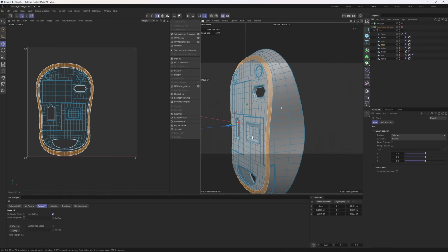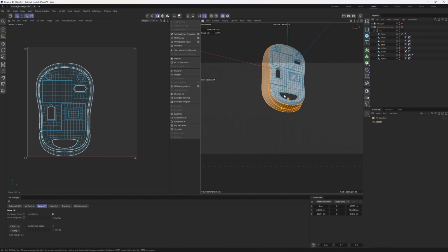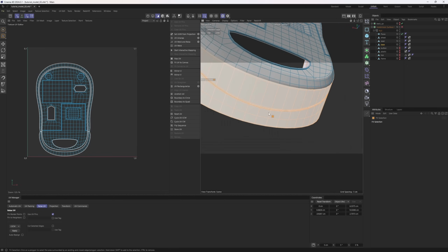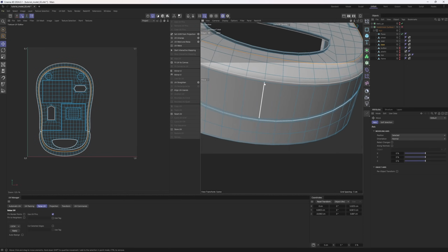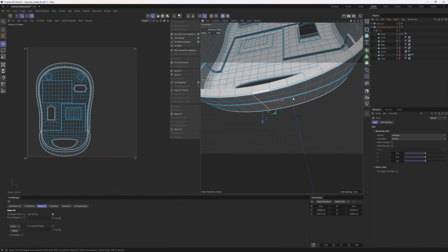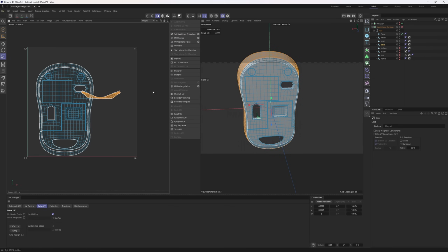Okay, then I will make another fill selection. This time, since this is a cylindrical surface, we will need an exit point, aka a seam. So I will select that edge, hold down Ctrl and Shift and select the last one. Now I want to make sure that this is selected. Click on OK. I will scale that up.